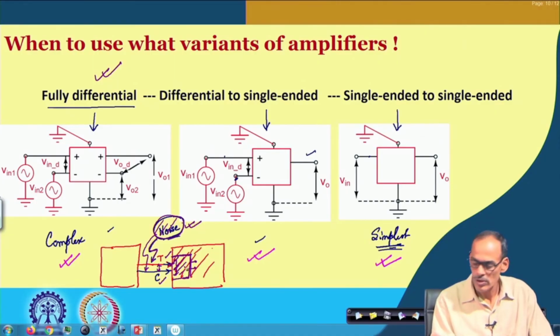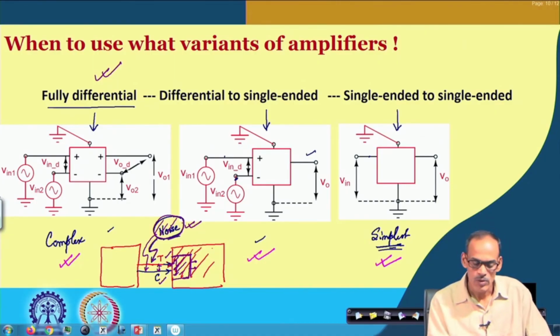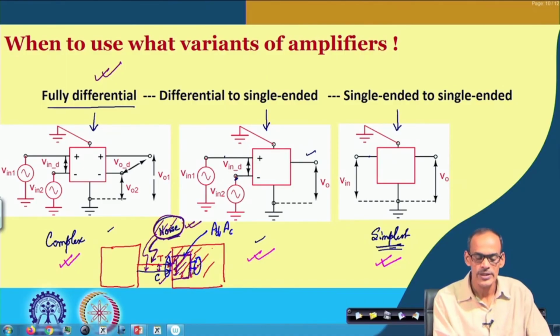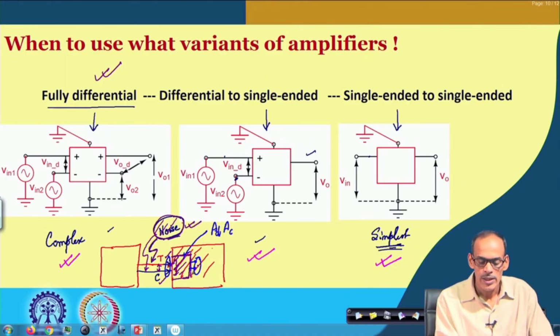Of course, it depends on what the differential mode gain and the common mode gain of this circuit are, but whenever we are seeing the output, probably the quality of the signal here will be much better compared to the signal here, because here the noise is getting suppressed. And if we are happy with the quality, probably in the subsequent block we can put single ended.